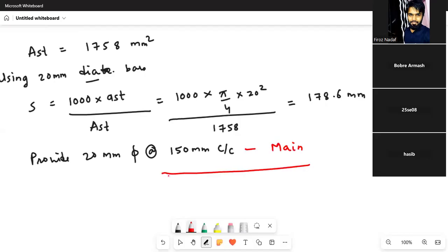See, this is your slab, or you can say deck in case of bridge, and you have gotten the main bar. And the main bar will be provided along the length of the slab. And since you have analyzed the slab, you may also have noted that it is a one-way slab. The deck slab is a one-way slab, and the main reinforcement will be provided along the length direction, because the length is smaller than the width. So the main bar will be provided along the shorter direction, along the length. Okay, width is more than length here.